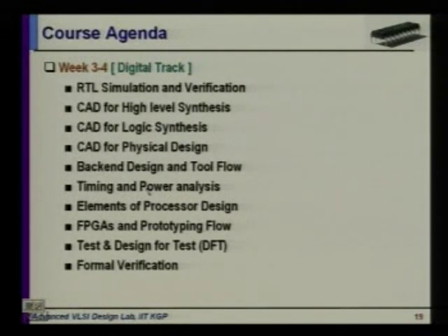This is the agenda for the digital track on the weeks 3 and 4. We are going to have RTL simulation and verification at the top level, and then you will have CAD for all the 3 levels: high level synthesis, which actually takes the design in Verilog or VHDL and synthesizes the design into logic, then logic synthesis and logic optimization, and then physical design, which is going to talk about layout, placement, routing, etc. Parallelly, you are also going to see back-end design and tool flow. All these steps.